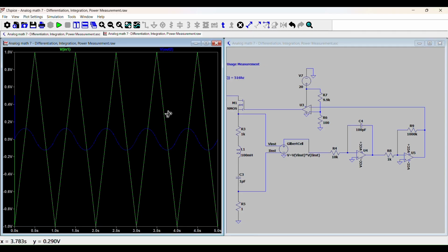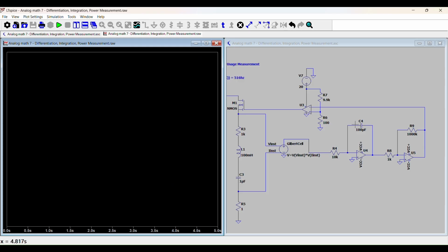power value. And the power calculation that I've set for this circuit is that the voltage output on this line indicates how many millijoules of energy has been outputted. So then there's a comparator here that compares this energy output to a set value. Here I've used a voltage divider to do that, and I've set it to 20 millijoules, essentially.